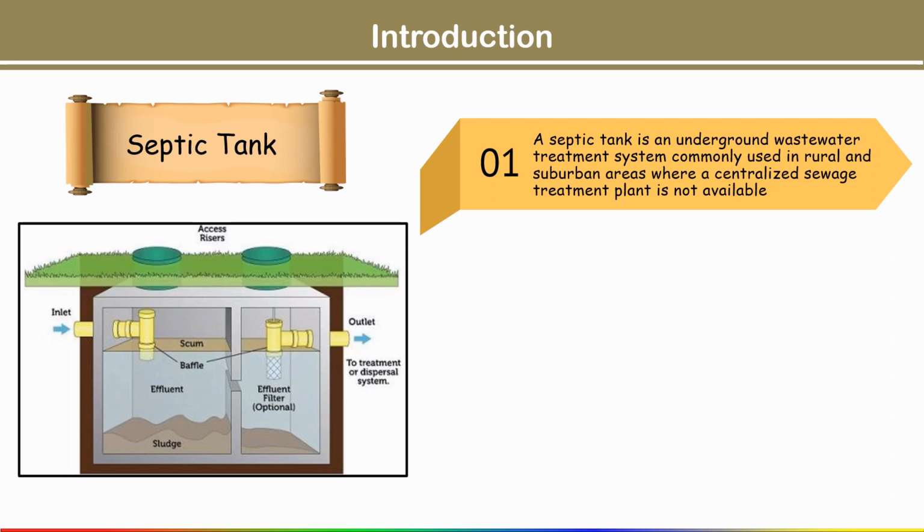After the manhole, we have a sewer line, or sewer pipe. In that sewer pipe, both the waste coming from the water closet and urinal, and the waste coming from the wash basin and shower, are running. That pipe we have to connect to the septic tank.